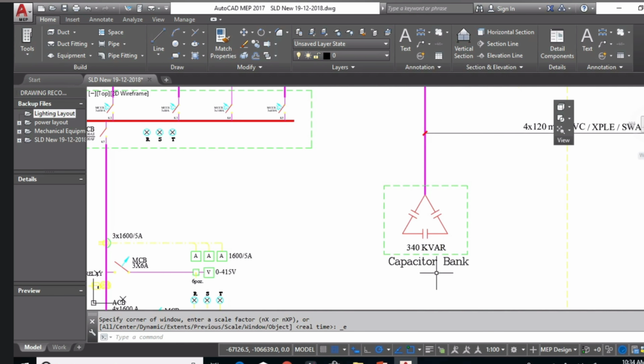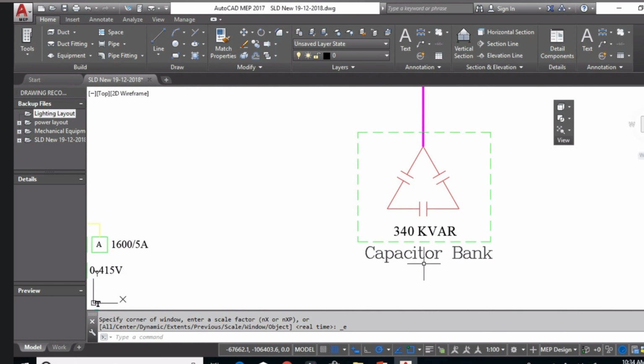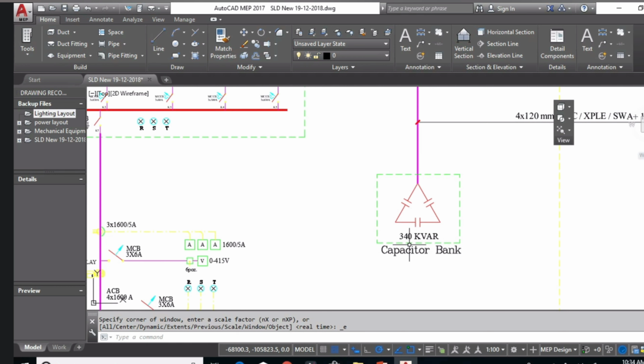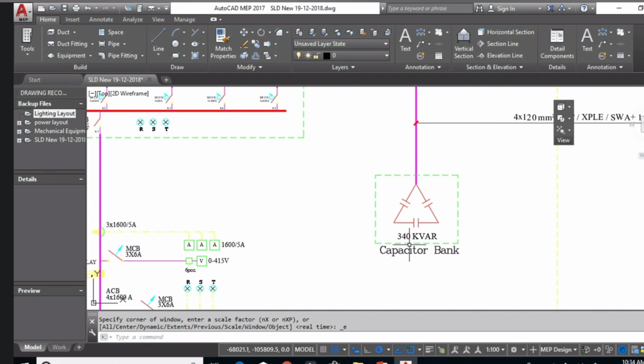And here, to enhance the power factor, I install the capacitor bank, and to size the capacitor bank for the whole 1000 kVA, I can choose 340 kilovar. Also I will attach for you one file that I made for one factory, designed for this capacitor bank or power factor correction.